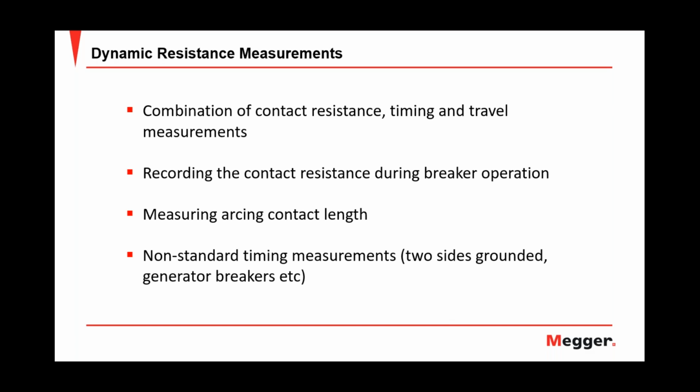This is performed by injecting DC current through the breaker and measuring the voltage drop and the current whilst the breaker is operated. A breaker analyzer, or the software on the computer, Cabowin, I mentioned earlier, then calculates and plots the resistance as a function of time. And added to that, if contact measurement is recorded simultaneously, you can read the resistance at each point of the contact, and this method is used for contact diagnosis, and in certain cases it can also be used for measuring times.